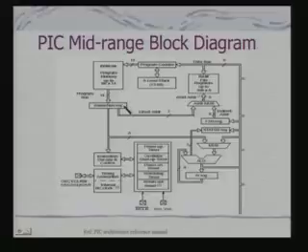This is your instruction register. Now this instruction register's basic job is to take the instruction. The instruction would correspond to what? The instruction whose address is provided by the program counter. This instruction is decoded by this block to generate what is called the control and the timing signals for the internal blocks of the PIC processor.